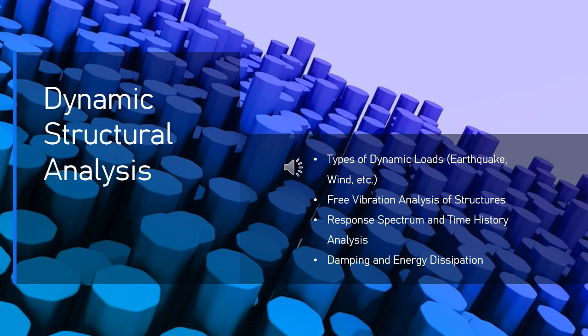2. Seismic design. Structures in earthquake-prone areas are especially vulnerable to resonance with seismic waves. Free vibration analysis helps determine the natural frequencies of buildings and bridges, which can then be used to ensure that the structure does not vibrate excessively during an earthquake. 3. Wind-induced oscillations. Tall buildings and bridges are susceptible to wind-induced vibrations. Free vibration analysis helps predict these vibrations and ensures that the structure has adequate damping or stiffness to mitigate them.